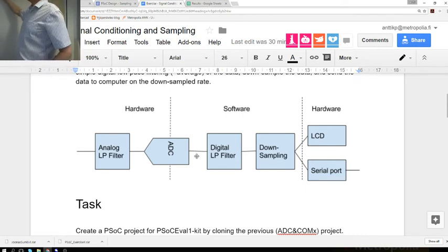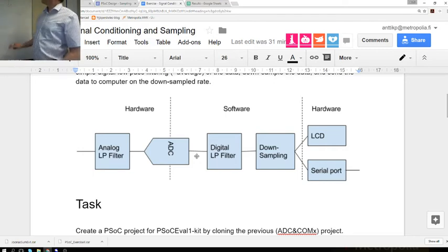So if we have a switch here, another switch here, and then we have a capacitor here. Basically, if you switch this one down, you can send a charge delta Q here, and when you open it and switch this one, you can actually move that charge here. So basically, the amount of charge transferred here depends on the voltage difference, right?